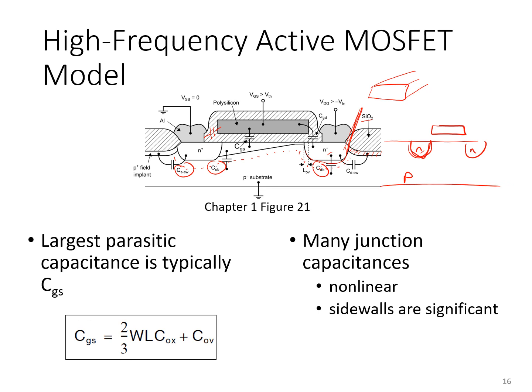Which may depend on how you lay this transistor out, what orientation you use, and anything you can do to effectively minimize the perimeter of the drain region can help to reduce the so-called sidewall capacitance, which again can be dominant even over the capacitance due to the bottom part of the drain junction. There's a similar sidewall capacitance formed on the source regions as well.